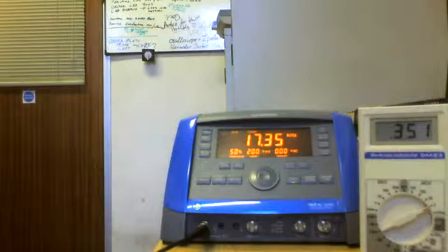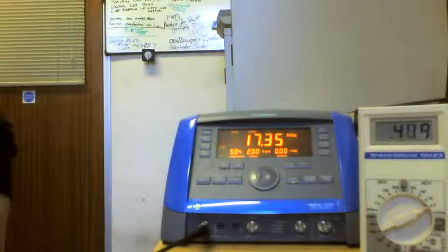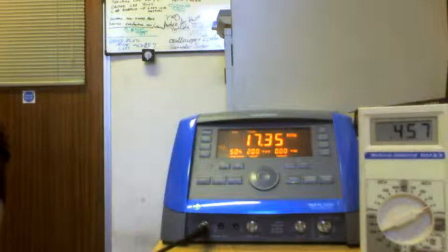Other things that I want to point out is that if you're actually measuring square waves, the RMS of a square wave, you can work this one out yourself if you want, is in actual fact half the peak to peak amplitude. Why is it half? Well, I'll give you a hint. It's on for as long as it's off. There you go.